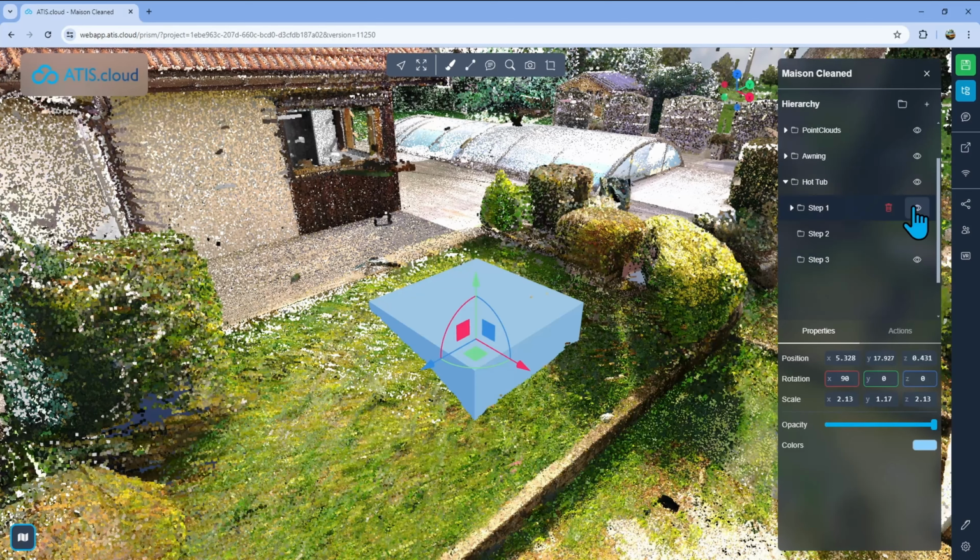So I'll put these two things. Don't show these. Show step 3. Select the clipping and just move it out there until it's only on that section. Doesn't have to be that wide, by the way. There we go. And so now all the way until that point. There we go. And we'll move it laterally until it hides everything. It's not wide enough. Doesn't matter. I just take that, make it wider, place it there, lock it, hide the frame, escape, and there we go.